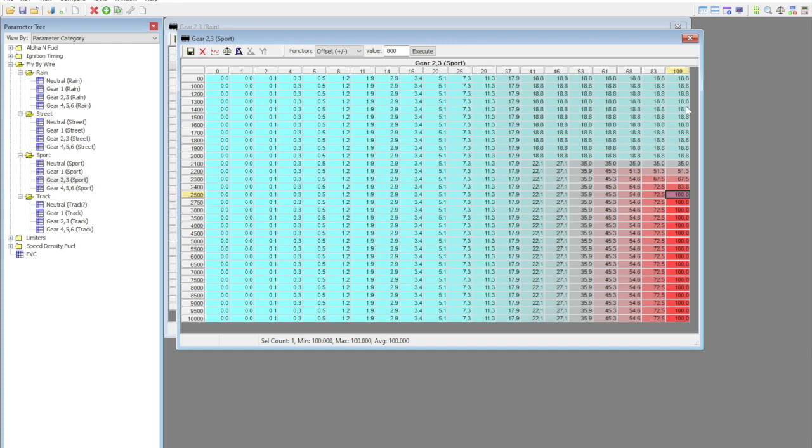That improves air-fuel mixing, homogenization, and power. So at high RPMs, you don't need to have that tumble because just the mass of the air going into the engine is good enough to generate that tumble. So by 2500 RPM, full throttle, good to go.